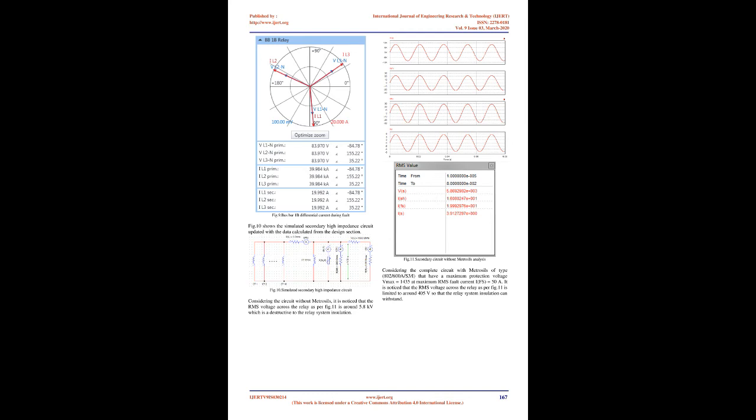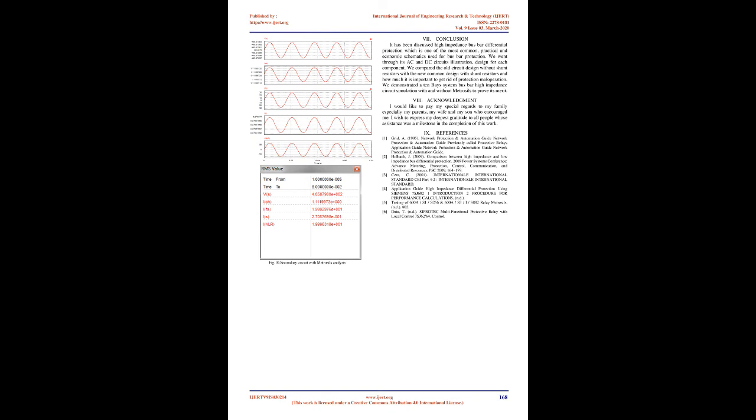operated, and a protective relay that could be in operated or not operated state. As per figure 5, the tripping criteria are contribution from both discriminative and check zones, where the discriminative zone supplies the positive terminal of the busbar trip relay 86BB and the check zone supplies the negative terminal. As per figure 6, there are 5 tripping cases out of a total of 9 cases. A correct tripping case should include at least a confirmed operation from one protection, either check or discriminative relays, and the other protection has either a confirmed operation, out of service, or CT supervision unhealthy. Busbar should not trip for the other 4 cases since there is no confirmed operation.